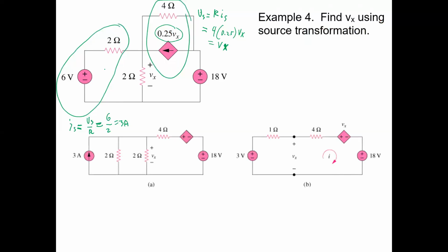So you can kind of see that when you do the resistors here in parallel, you can actually gobble those up. And then you can see by looking ahead, right? Then you have these things in series. That makes it a little bit easier to analyze. If they're still in parallel, it becomes a bit cumbersome to deal with that circuit. Whereas when you finally have it as a single loop here, then it becomes a simple thing to analyze.